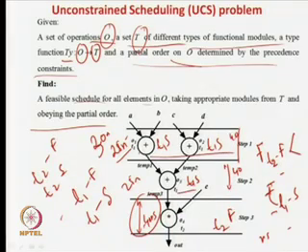So, we will take a slow adder, because a slow adder takes very little area and very little power. So, I will use slow adders over here and I will use a fast multiplier over here. That is actually called the binding allocation problem.